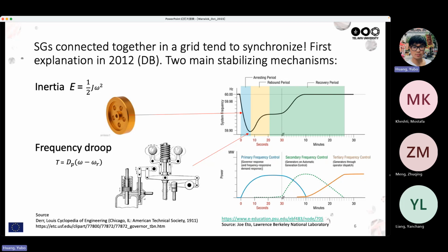And how do we notice that it becomes unstable? Not necessarily that it suddenly gets out of synchronism, but it is less tolerant to perturbations. So the main perturbations are short circuits on lines and generator faults. When a generator suddenly has some fault and it shuts down, then you lose generating power, and it's the same effect as a sudden increase in consumption.